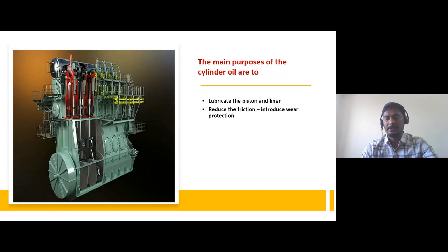It can improve the wear protection, so minimize the risks of scuffing. The lubricant helps to reduce the gap between the liner and the piston ring, so it does not allow blow-by combustion byproducts into the system. It also neutralizes acids and oxidation byproducts according to engine requirements.